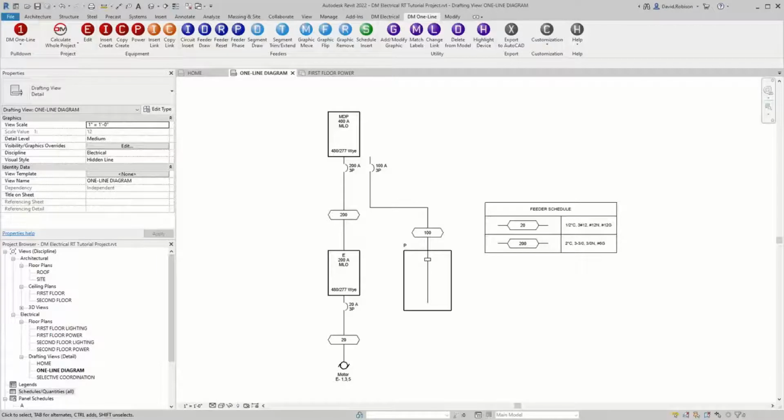The final question that I had was, how do you get a transformer primary without a neutral? So getting neutrals right in Revit is tricky. They did not implement neutrals in the way that I would have necessarily implemented neutrals, but we have to work with what Revit gives us. So the way you handle neutrals actually varies depending on whether you're doing distribution equipment or a branch circuit. Essentially a feeder and a branch circuit you want to handle differently just because Revit handles them a little bit differently. And so we need to have a little better nuance for what's going on there.